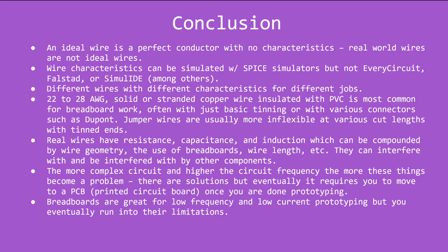Real wires have properties, resistance, capacitance, inductance, that could all be compounded by wire geometry, use of breadboards, wire length, etc. They can both interfere with and be interfered with by other components. The more complex and higher frequency a circuit becomes, the more these things become a problem. There are plenty of solutions, but eventually you might want to think about moving to printed circuit boards. Breadboards are nevertheless good enough for low frequency and low current work, but you'll eventually run into their limitations.